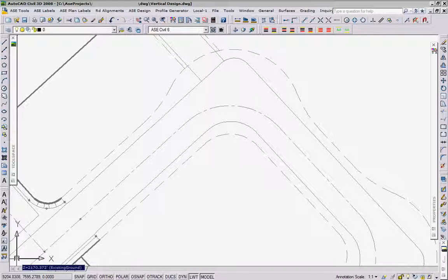Since this particular site design included a section of road that has no curb, we'll have to insert more design markers along the edge of pavement to ensure that this is modeled. The objects where we placed these design markers did not exist on control layers when we defined the base map control.